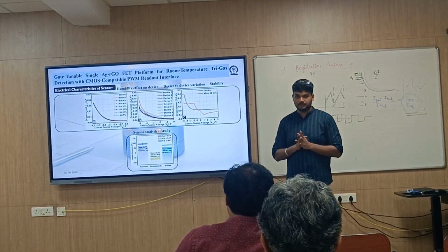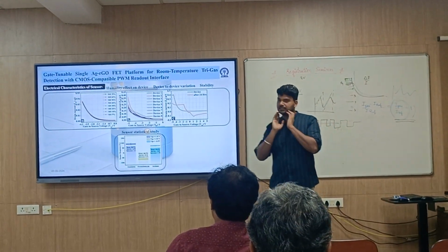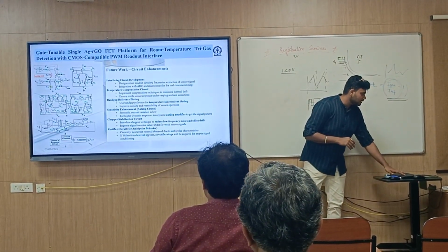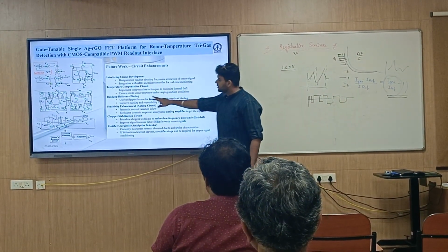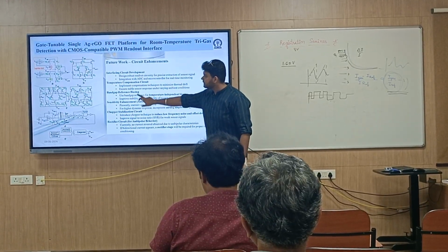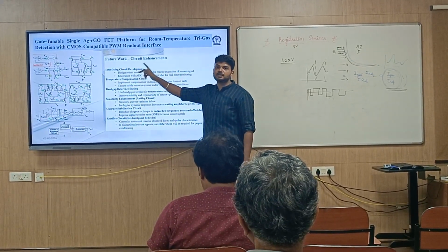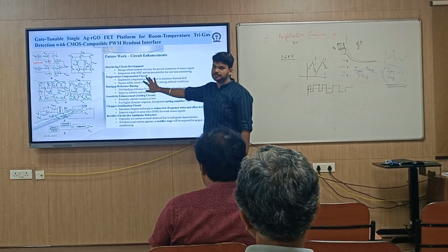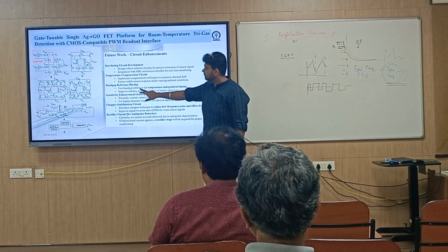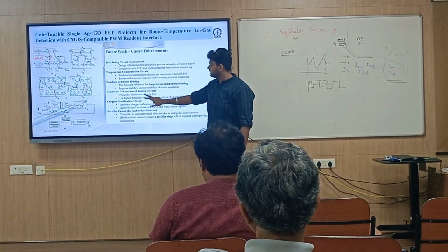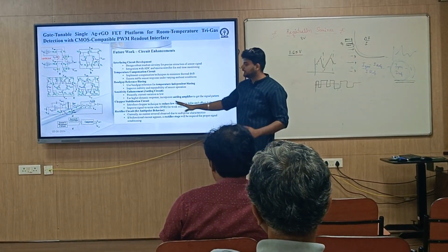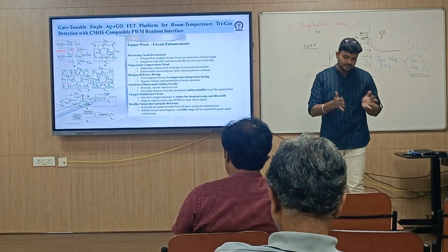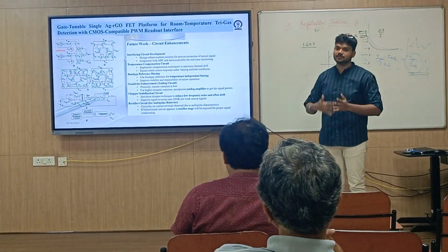Yes, it has affected the performance. Please take a look at that. So next, it is the same. We have to add noise compensation, sensitivity enhancement, and temperature compensation, because right now what we have is not temperature compensating. Band gap reference biasing, chopper stabilization, so many things we have to add. Simultaneously the sensors, the circuit and the ML part are going on.